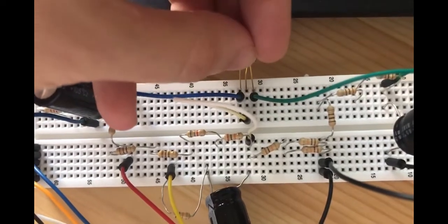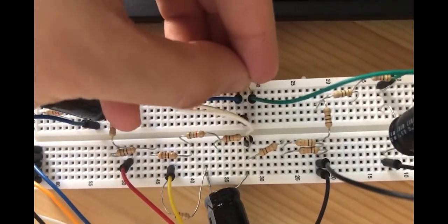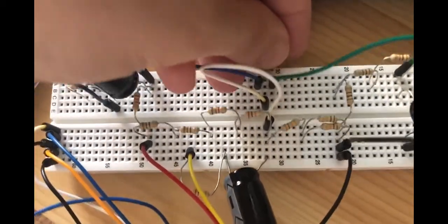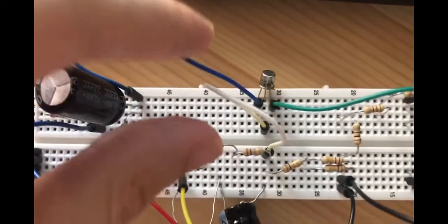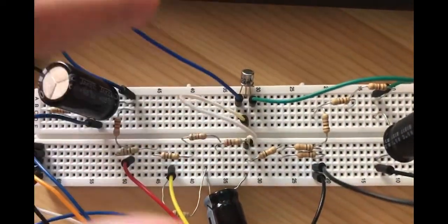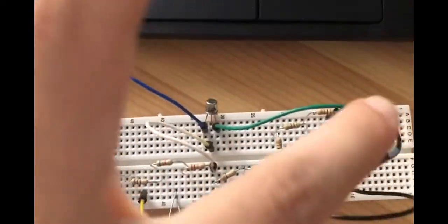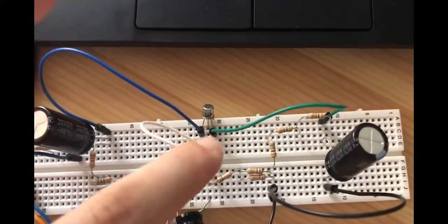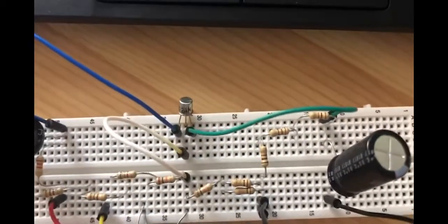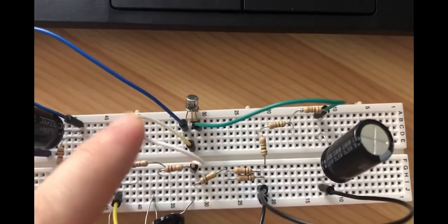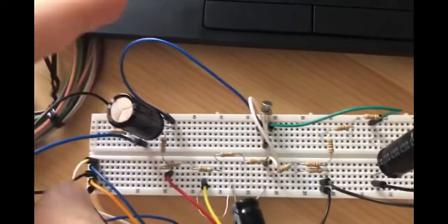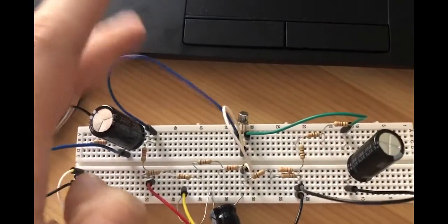I have made my circuit in a way that these three go like this. You can see it, the notch is on the right and the base is the middle one and the left one is the collector. I use the green wire to bring the emitter node to somewhere in this distance from the BJT, and the white wire is for the base and the blue wire is for the collector.